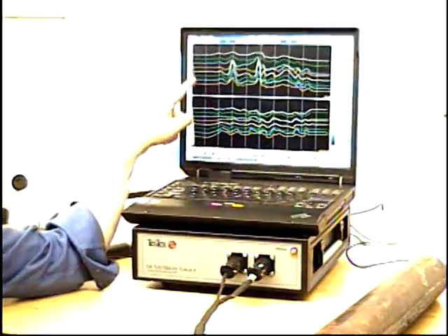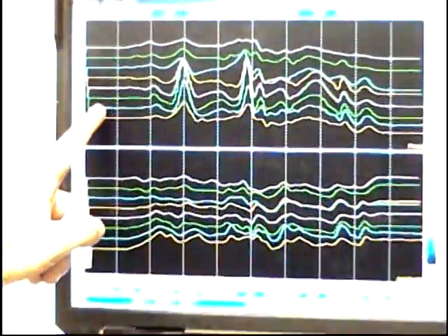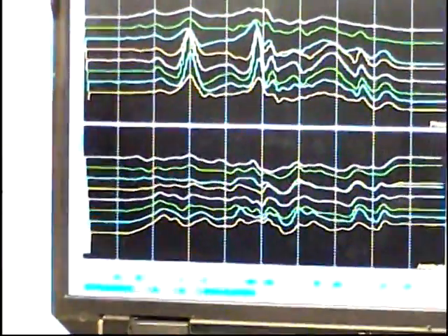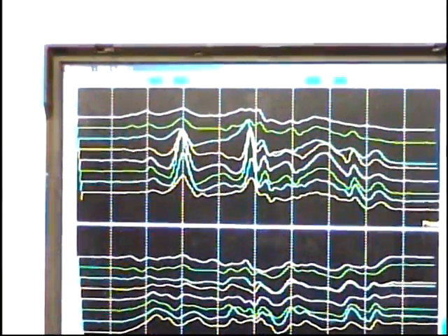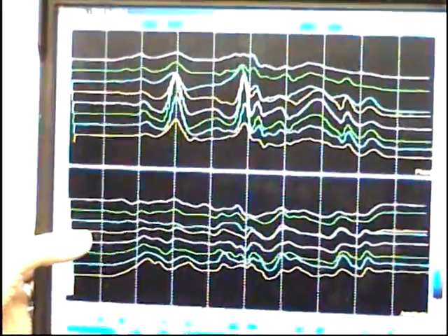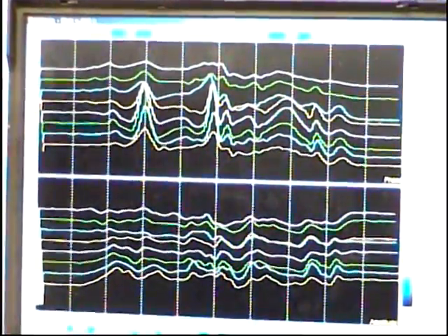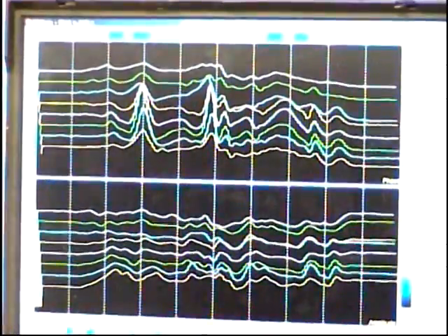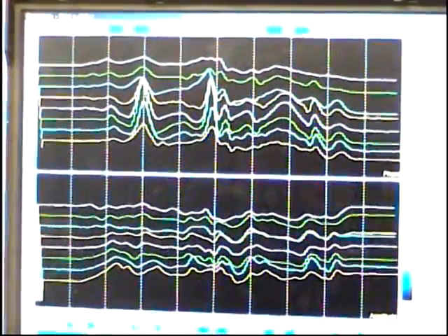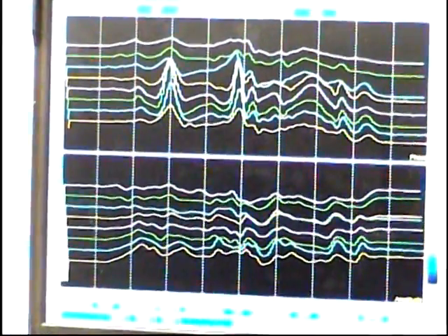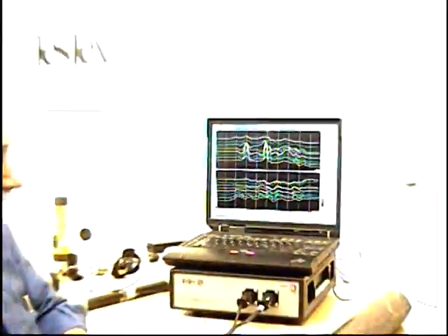Looking at our signal, we have our phase and amplitude. By looking at our phase, we can give an approximation of what the diameter is. Our amplitude gives us the volume, in other words, how deep the flaw is. Before we come out on site, we want to make sure we have the proper calibration. So if the tube is a 3-inch 250, we'll run the machine over flaws of maybe 20, 40, 60%, so that when we come out on site, we can make a calibration and size any flaws that we find.